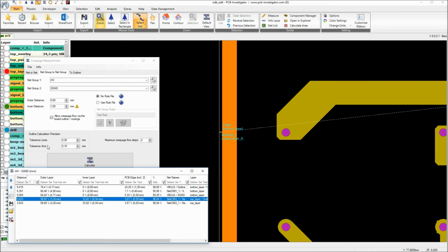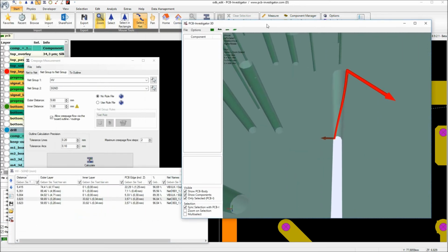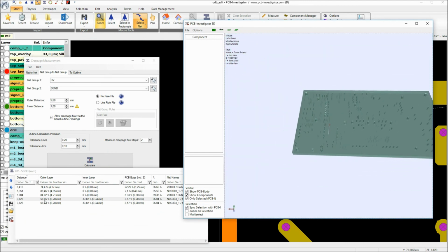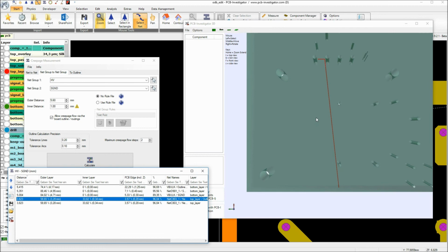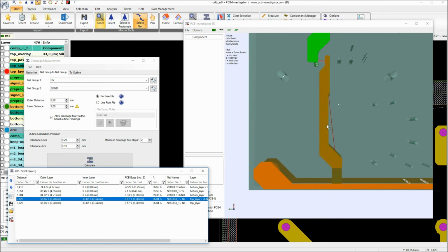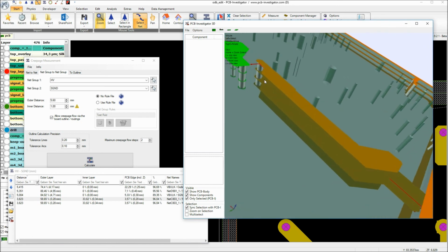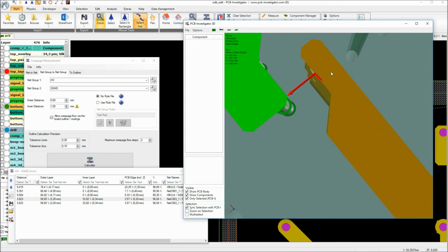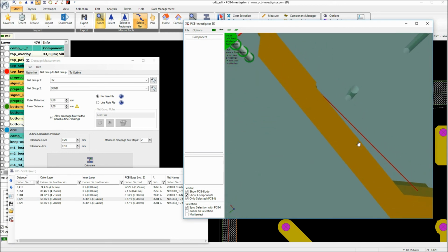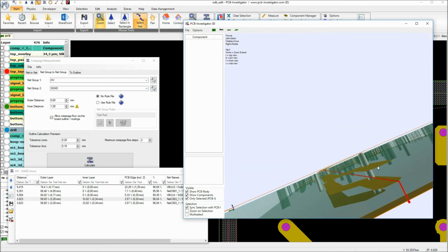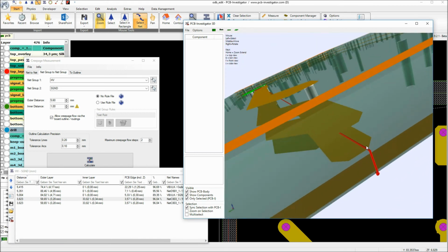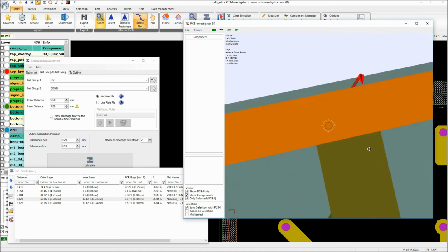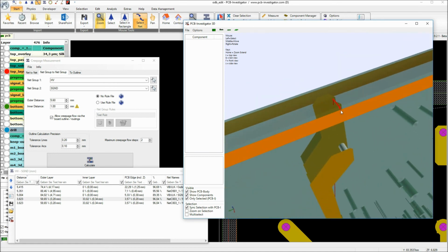And this one is also quite interesting to see again in 3D. So I repeat in 3D here, synchronize this one and select also the nets. What we can see is on the top layer we go from the high voltage net into this totally independent copper. Then we go through this copper to the outer edge on signal 2, go to the PCB edge, and the creepage is going down on the outer corner and entering the SG&D on the bottom layer here.